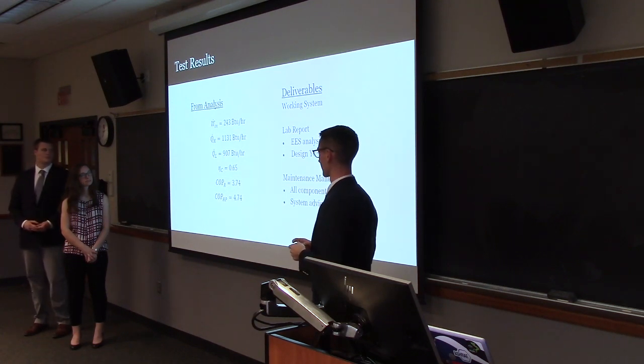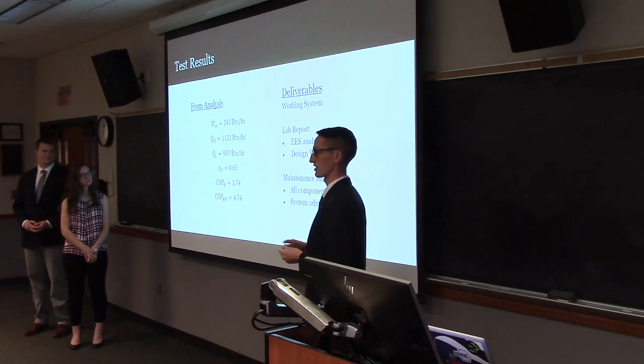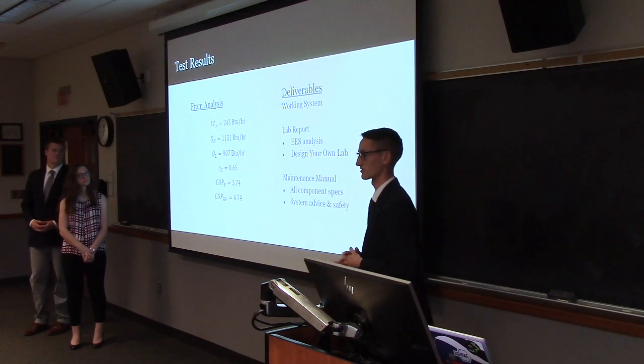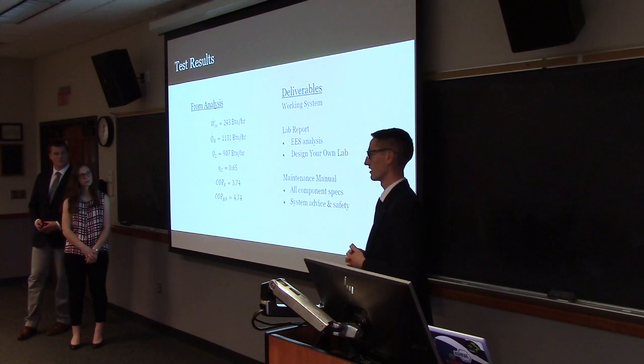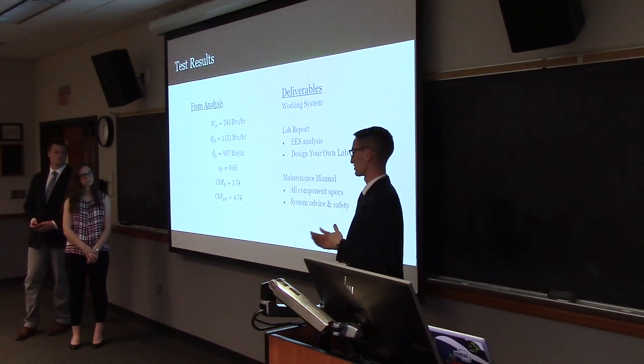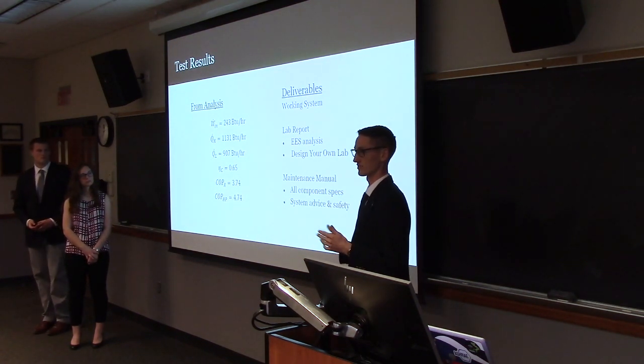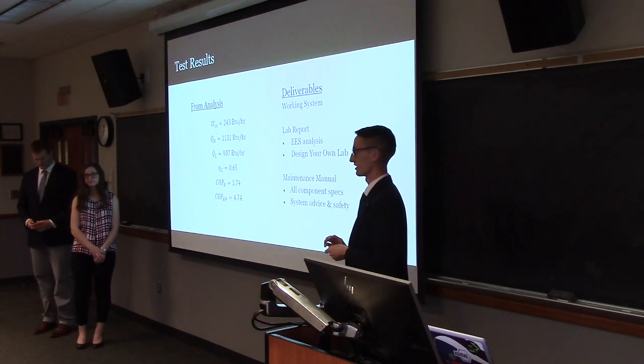But the really interesting part, I think, is with the efficiency of the compressor. For most commercial compressors of the size that we have, which is a third of a horsepower, the efficiency is anywhere between 0.4 and 0.7. So we're kind of in the middle range there.